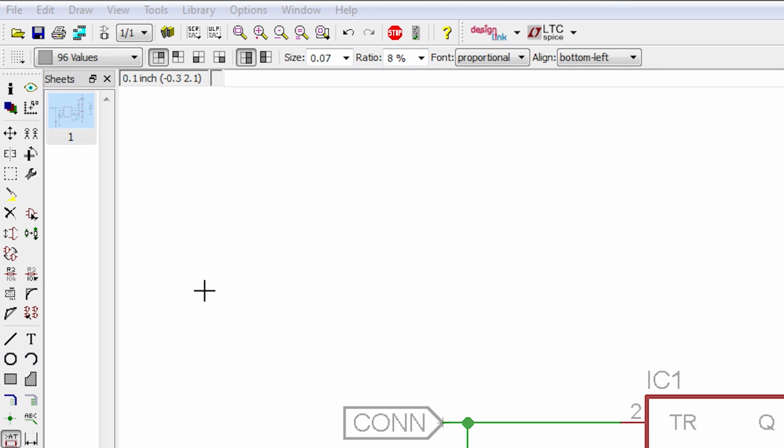Of course, you can also manually generate a BOM for DigiKey or Mouser or any other electronics distributor, and I'll often do that. Or you can also go find plenty of user scripts that plug into Eagle that generate BOMs for all kinds of suppliers. But we'll use the Design Link tool because it's built in and it's pretty easy.